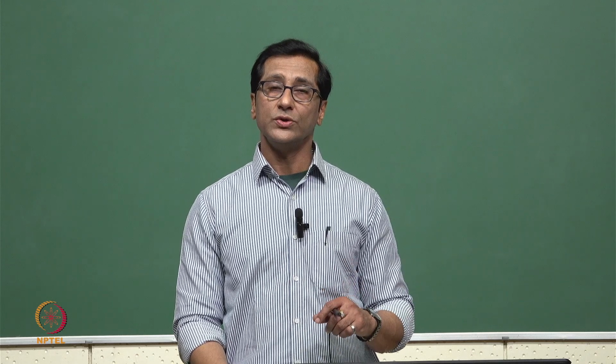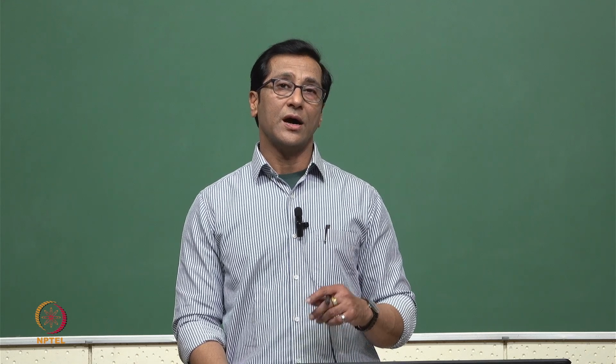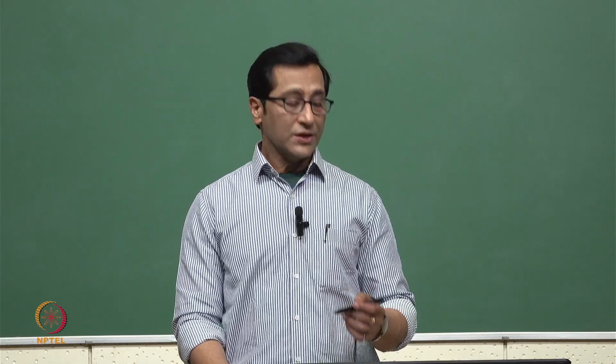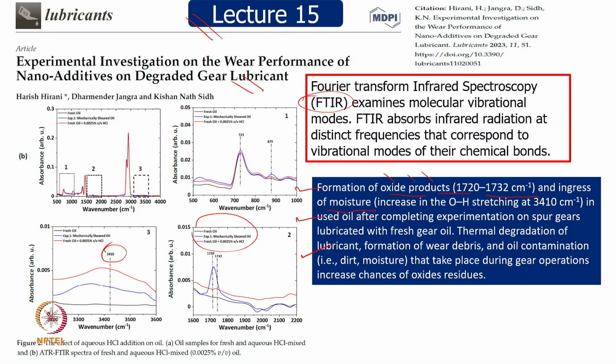Now if we do some sort of sensing, or we come up with a better sensor, this offline analysis can be shifted to in situ analysis, and that will be helpful to the digital twin. That's why we have been talking about something like a pH sensor, which can be integrated with the gear system, or gear setup, so that we can do in situ measurement of the pH level of the oil,